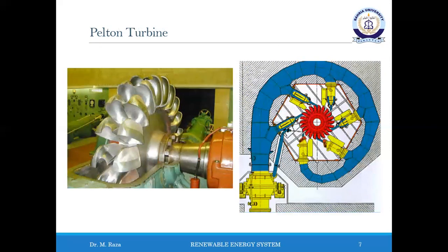The efficiency of a Pelton wheel is greatest when the speed of the cup is half the speed of the water jet. As the cup speed depends on the rate of rotation and the wheel diameter, and the water speed depends on the head, there is an optimum relationship between these three factors.